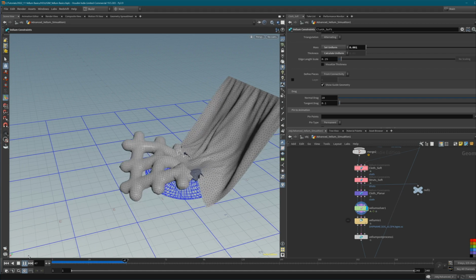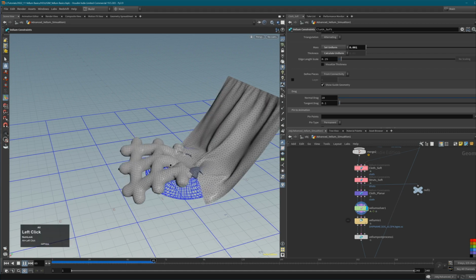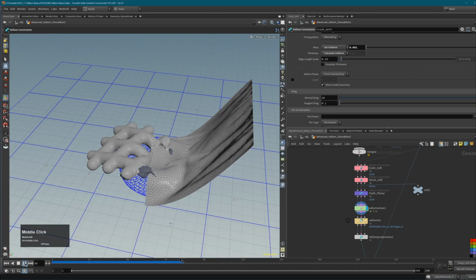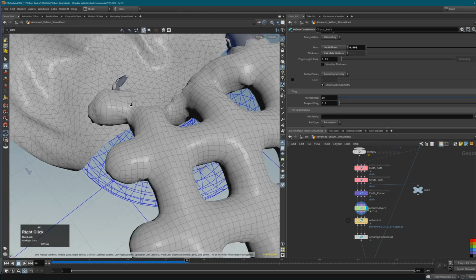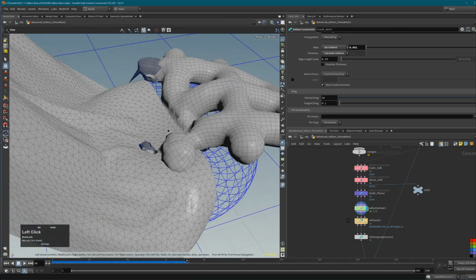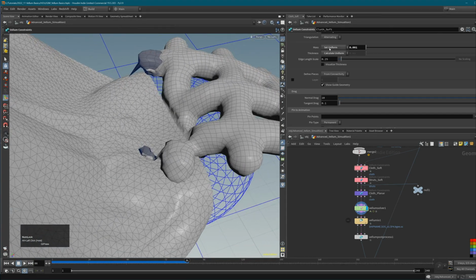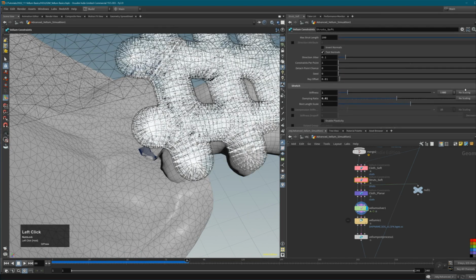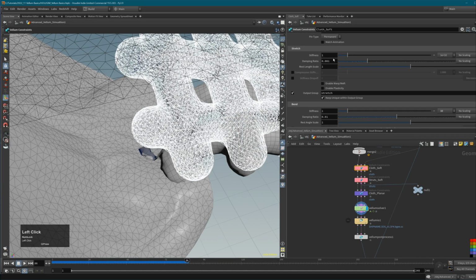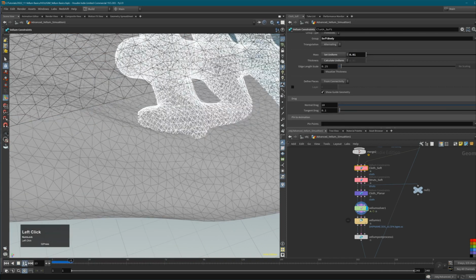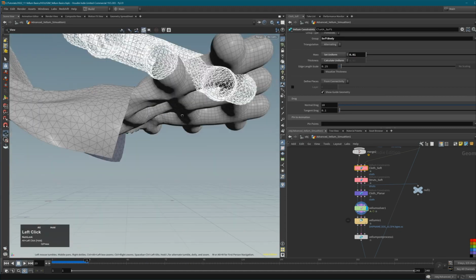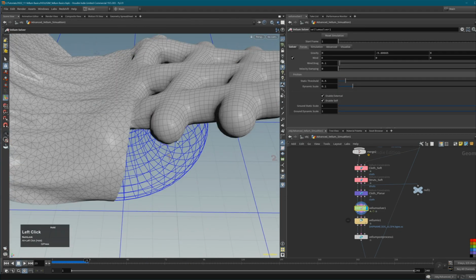And now, okay, now I have some very strange collisions here. And this is also a good example. Good that this happened. So what we have here now is actually very ugly results. And sometimes this happens in Vellum. So first of all, I would say that this weight is not good with these struts. So now the struts are way too stiff and the weight is way too low. So let's maybe increase this a little bit so that it doesn't give us such crazy results. Something like that. And let's re-simulate this. Let's see what kind of deformations we get now.